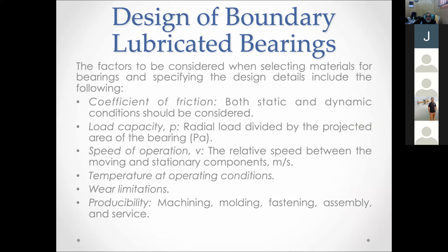So design of boundary lubrication bearings. So how do we design the boundary lubricated bearings? The factors to be considered when selecting materials for bearings and specify the design details include the following. Coefficient of friction, both static and dynamic conditions should be considered.